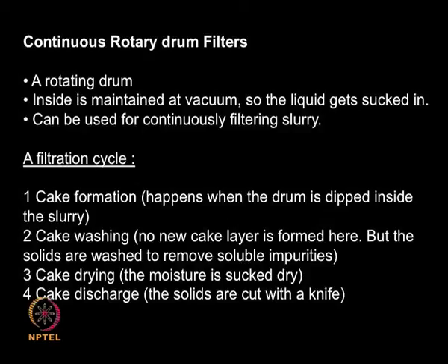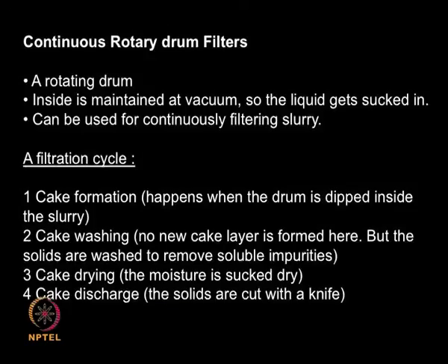Now we looked at simple filtration setups and we also looked at some of the equations for filtering slurry when there is a compressible bed or when the bed is incompressible, or when the filter medium offers some resistance or does not offer any resistance. Now let us look at another type of filtration. I showed you a picture of that before as well. It is a continuous rotary drum filter.